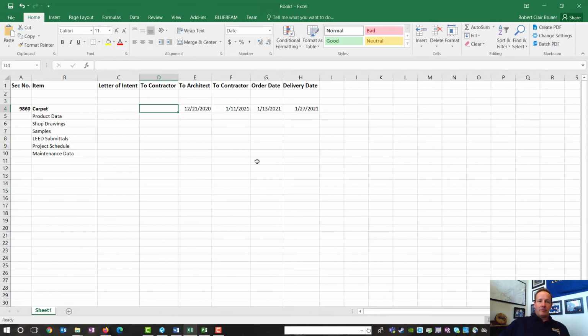Now from the contractor to the architect, that is the review time for the contractor. The contractor will usually try to get these reviewed pretty quick before they send them to the architect. And there might also be time if the contractor rejects it and sends it back to the subcontractor, so you need some buffer time in there. Usually you try to get them reviewed in a week. Let's give the contractor 2 weeks just in case we need to get these submittals redone. So we're going to take this date minus 14 days.